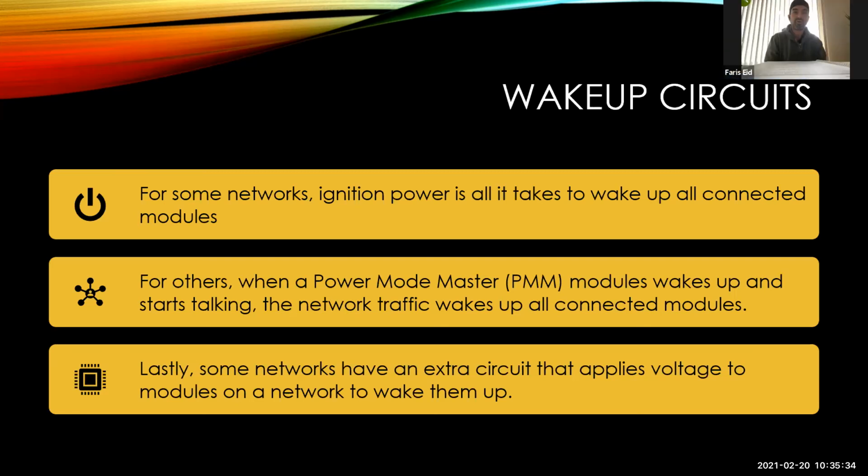And Mitchell tends not to tell you that. It's not lazy, that's smart. Yeah. No, absolutely. If I know why the computer's mad, why did it set a code? If I can get that and a wiring schematic, I can figure the thing out. I don't need a flow chart.